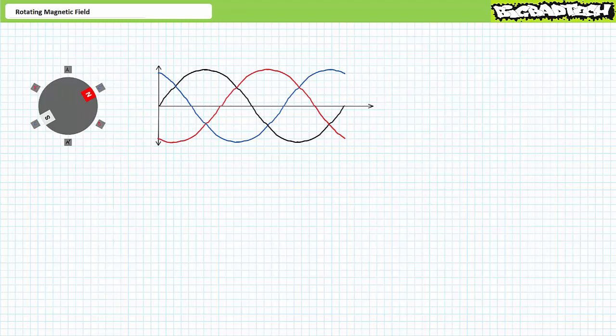Ideally, we should see the stator establish a rotating magnetic field such that the rotor is dragged in a full circle. With 6 total poles, we have effectively divided this full circle into 1/6 of 360, or 60-degree angular increments. The first interesting thing happens when L2 peaks negatively. B becomes the south. B' is a north. The north end of the rotor is attracted to B, and the south end of the rotor is attracted to B'. The motor turns clockwise.